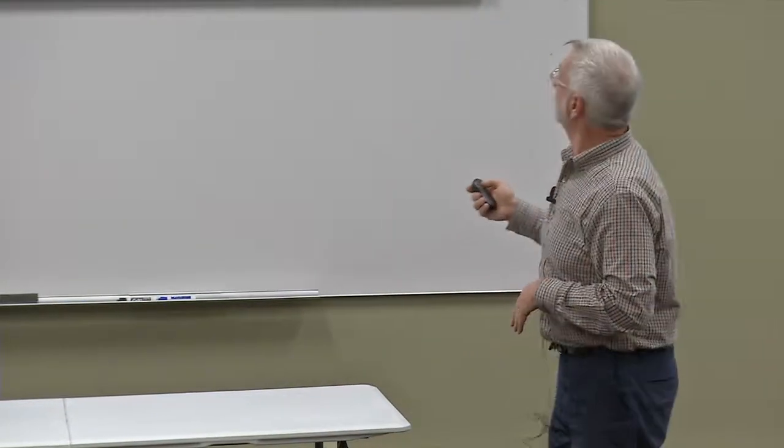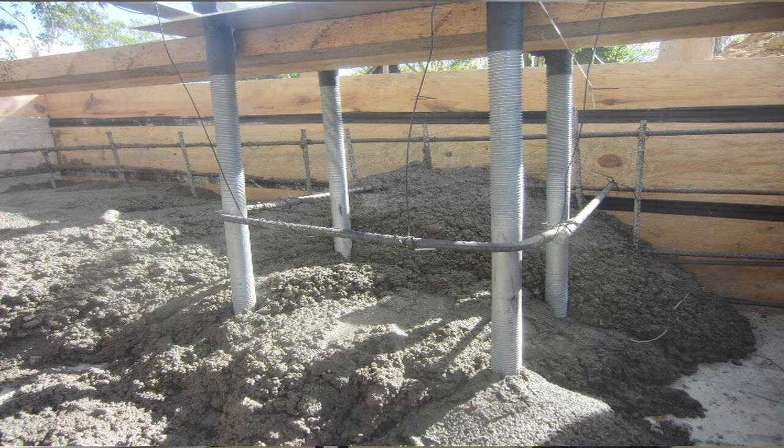So, there again, contractor problem. Okay, here's our anchor bolts here. This is an addition that we added to it here. The design did not call for any kind of reinforcing to tie the anchor bolts into the rest of the foundation, but we felt like it was a good idea. This is not uncommon practice.